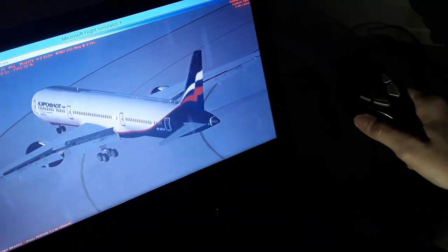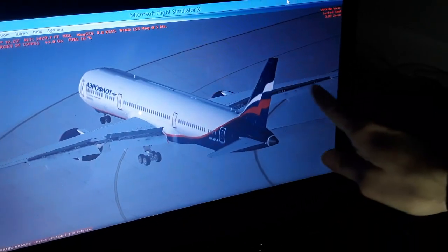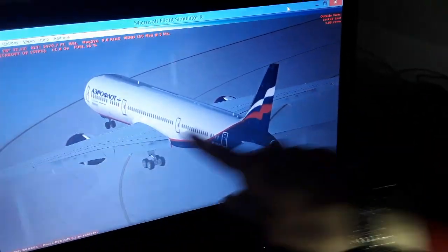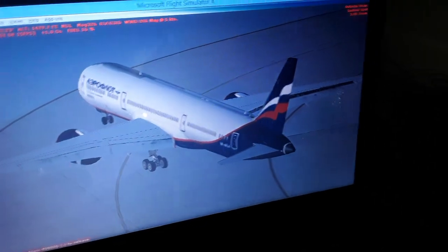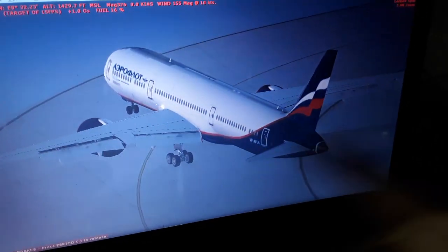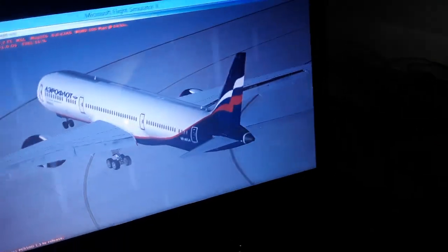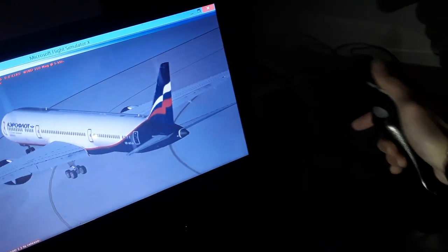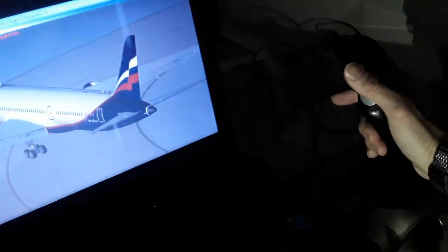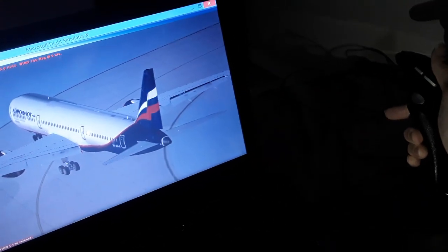In the Airbus we use ailerons and spoilers on the left and right wing. You can see ailerons and spoilers extended. So we use ailerons and spoilers to make either a left or right turn by making differential pressure. So this is a left turn, this is a right turn, differential lift. So you roll left and right, very easy, very safe to use because you can climb or descend at the same time. There is no problem using all flight controls together, to have coordinated flight.